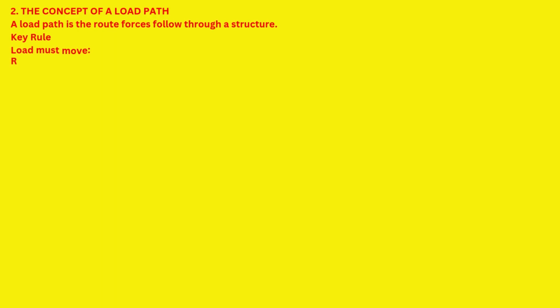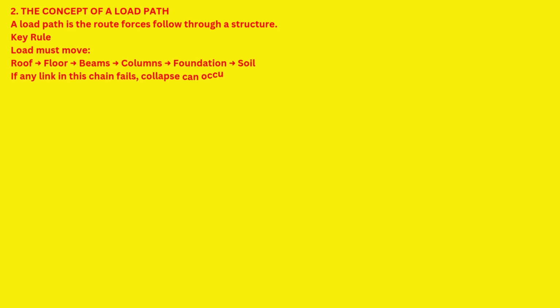2. The concept of a load path. A load path is the route forces follow through a structure. The rule: load must move. Roof, floor, beams, columns, foundation, soil. If any link in this chain fails, collapse can occur.